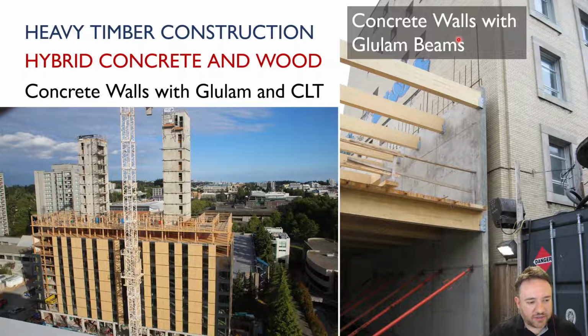Concrete is another thing that is combined with timber very often, and the reason being that in the early days of CLT, people were a bit gun shy about making the elevator cores and the primary egress, like emergency exits, out of wood because it is combustible. Now, there's definitely ways to get around that, mostly involving encapsulating those timber elements in heavy layers of gypsum.